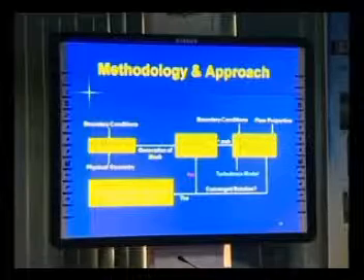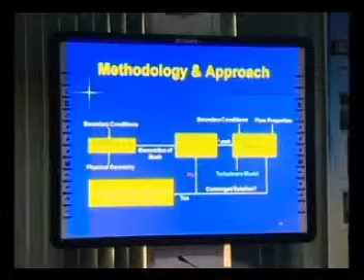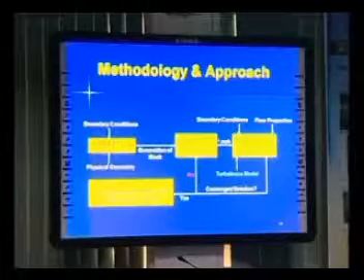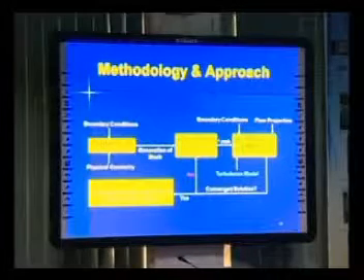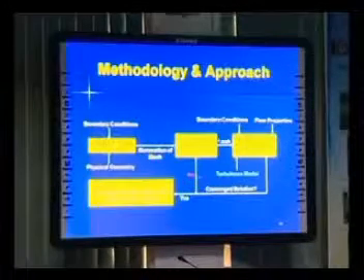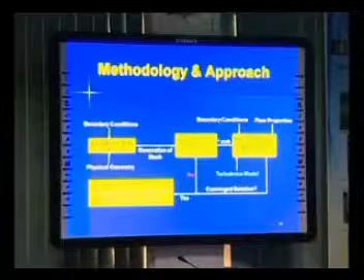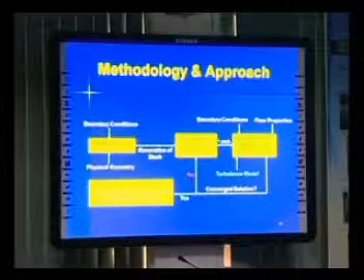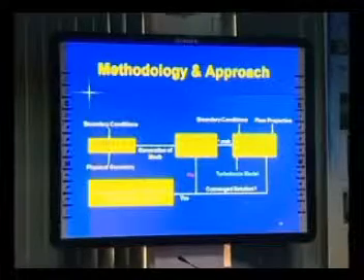So you have to make sure that you finally obtain a converged solution. Then you get numerical data, graphics, and different kinds of plots at your disposal. And if you don't get a converged solution, you have to go back and look where you went wrong in the computational model. You have to keep looking for a realistic, converged solution until you get what you desire.